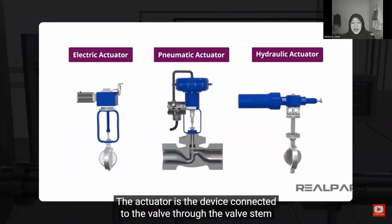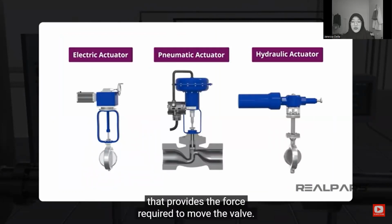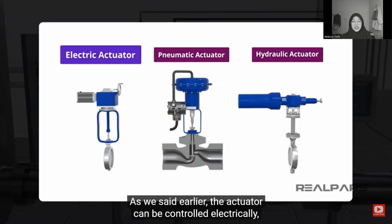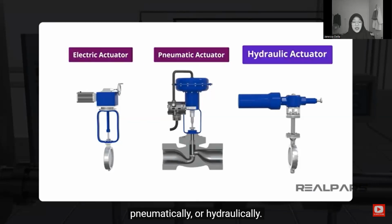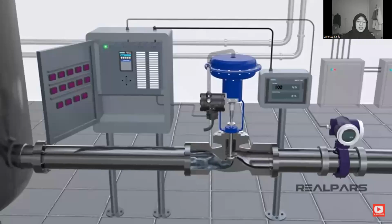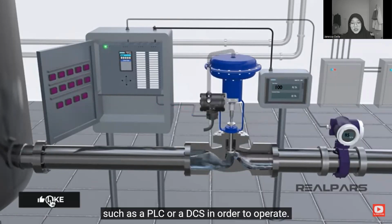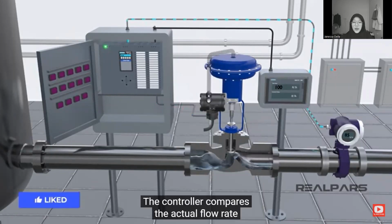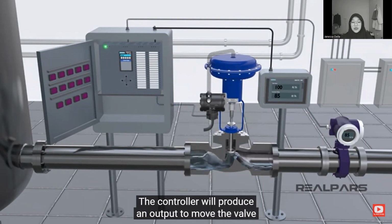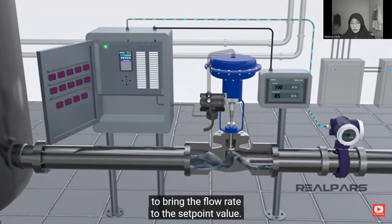The actuator is the device connected to the valve through the valve stem that provides the force required to move the valve. As we said earlier, the actuator can be controlled electrically, pneumatically, and hydraulically. The most common and the most reliable is the pneumatic actuator. The control valve receives a signal from a controller, such as a PLC or DCS, in order to operate. The controller compares the actual flow rate to the desired flow value called the set point. The controller will produce an output to move the valve to bring the flow rate to the set point value.